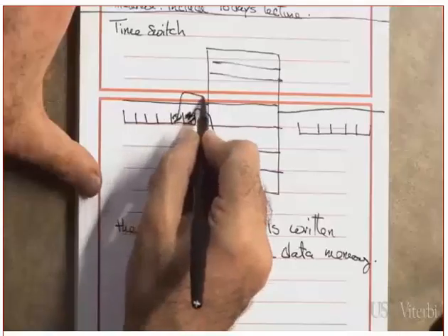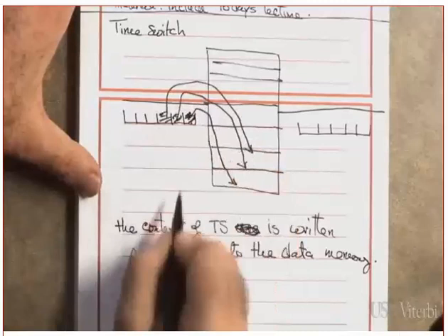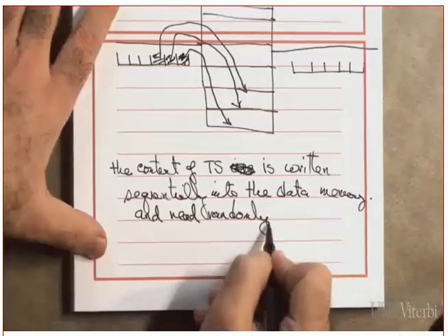Now, by how many time slots? By 2 time slots. It got delayed by 2 time slots. So the time switch introduces delay, whereas the space switch does not introduce delay, because the space switch does not switch time slots. Did you get this or not? So this one got read in here.